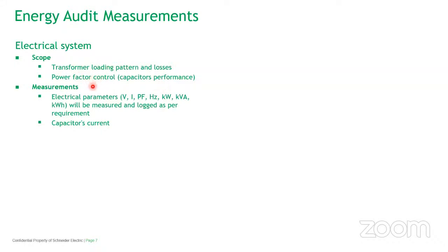If the power factor is very low, that means your losses are more, electrical distribution losses will be more. So in industries or buildings, we see that power factor is maintained at 0.99. Many states have gone with kVAh billing, where they want to recover the losses indirectly. But in Karnataka and many states, we are still on kWh billing. So this power factor plays a very important role here, and we need to measure the data.